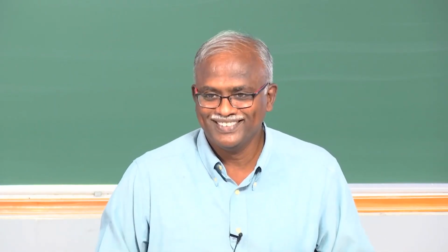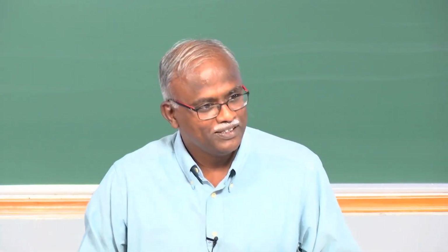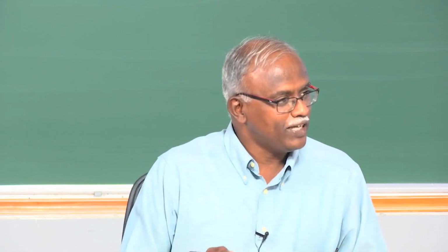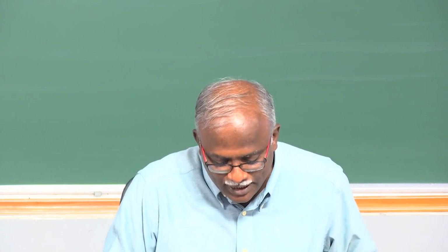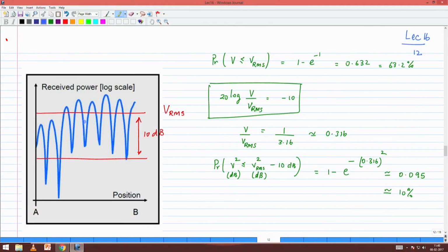Which is better? Fast is better. Everybody would agree fast is better because you don't get stuck in a bad situation. Because what would happen if you sat in a bad situation? It says bad, call drop, gone. Because the speech coder cannot survive beyond a certain point, and you've already allowed for 10 dB margin, and this has gone below the 10 dB margin, and therefore you're killed. So the good news is, move fast. Don't walk slowly, move fast. But you can't control the user behavior.